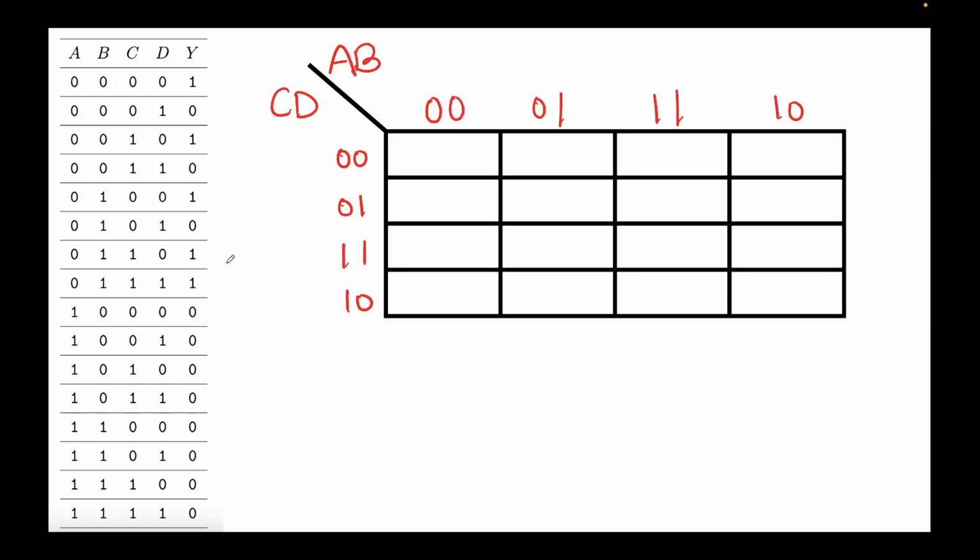So the way to approach is that this is the truth table that we know. What we'll do is draw a K-map corresponding to this truth table. So we saw this earlier also. There are 4 inputs, A, B, C, and D. So AB will denote the columns, CD will denote the rows. As I told you, from one column to other, there can be a jump of only 1. So you see only B is jumping from 0 to 1. A does not change. Similarly, from second to third column, B remains 1 to 1, but A jumps from 0 to 1. Similarly, for third to fourth, B changes from 1 to 0, while A does not change. And from fourth to first, you see A changes from 1 to 0, while B does not change. Similarly, you can see for the rows.